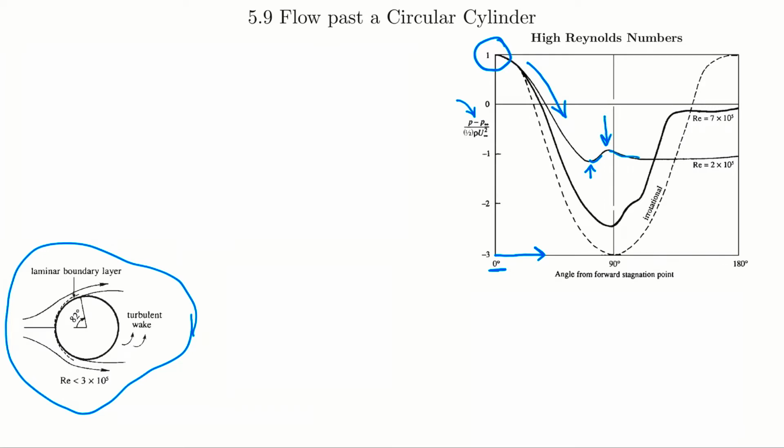And then what this plot is showing us is that with very little change, we get basically the same pressure all the way along the back. After this point of separation, shown right here and here, all along the back surface we have this lower pressure, much lower than what was at the front of the sphere up here. So much higher pressure here, lower pressure here, high P, low P, and that causes a substantial pressure drag, where you get a lot of force pulling back against this circular cylinder.